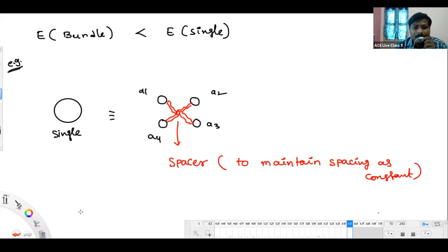Here we have taken only one conductor, which is sufficient, Bhavana. Why are you bothering about summation again? Not the total bundle. Only one subconductor you have to find, because the field intensity at that place decides the corona. That's it, not the summation.